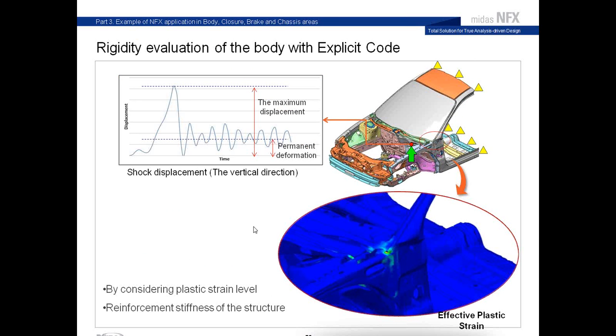So the displacement will give you a maximum displacement, and you will be able to see the plastic strain level and where you also need to reinforce your structure.